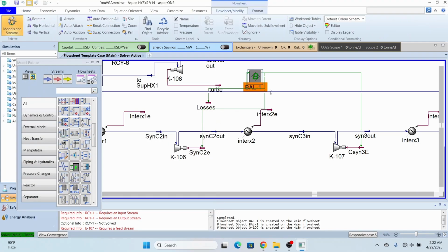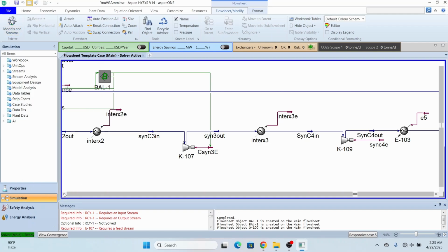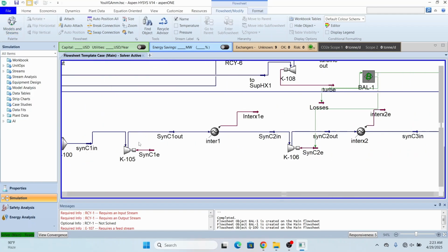So what we have done is use the energy, or the heat flow or power, generated by this steam turbine to run the two shafts of our second and third stage compressors. For the remaining power, you can see that here it is 5,000, and the first stage compressor also uses 5,000 kilowatt of power.